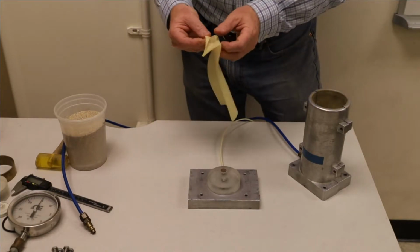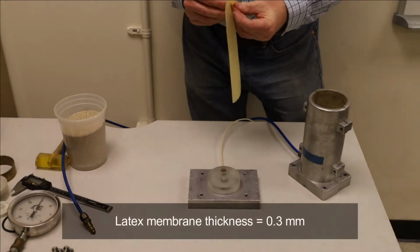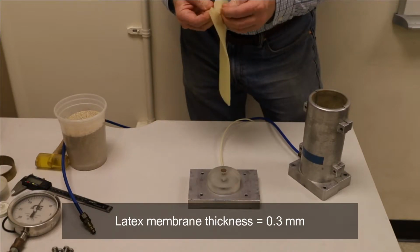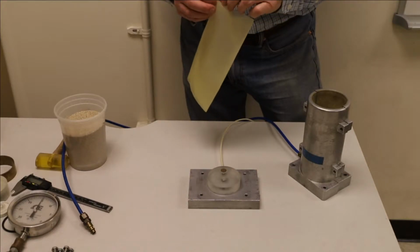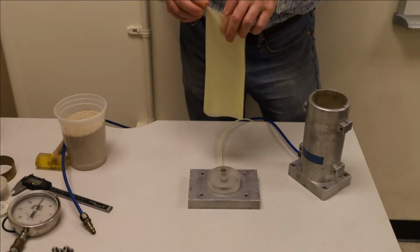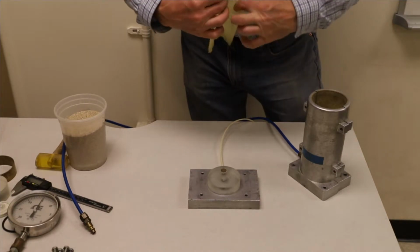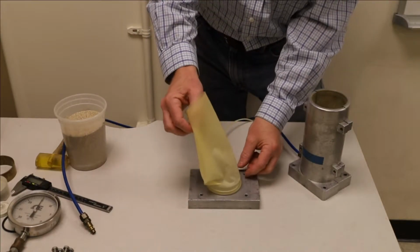So the first thing we're going to do is take the latex membrane, which is 0.3 millimeters in thickness, and we're going to connect that to the bottom cap, and it needs to be sealed because we need to maintain a pressure difference of whatever vacuum confinement we decide to apply during the shearing.